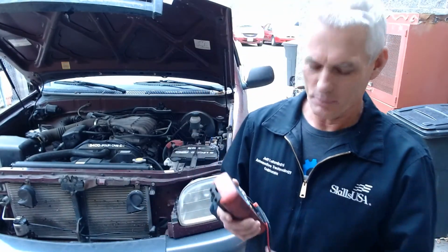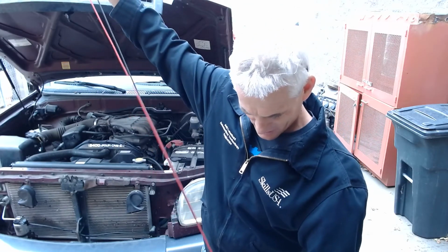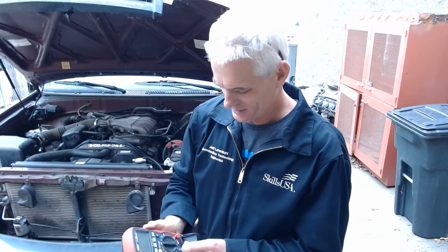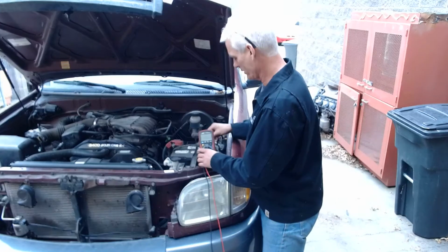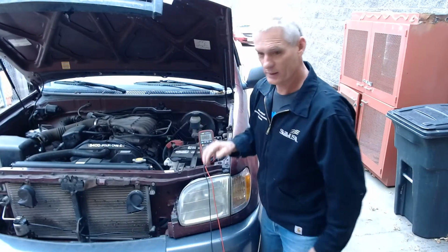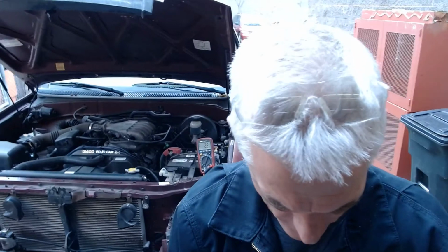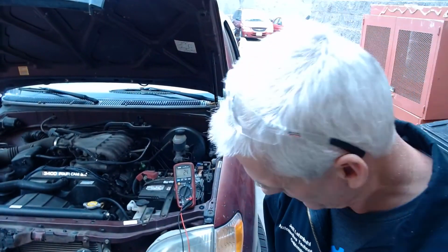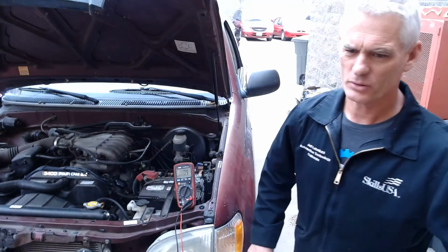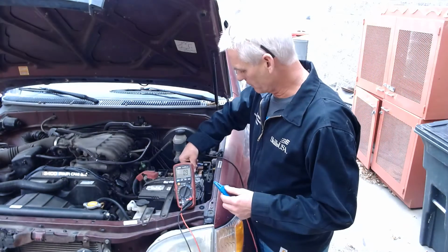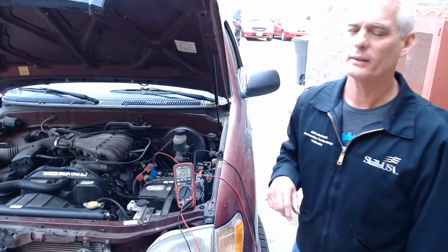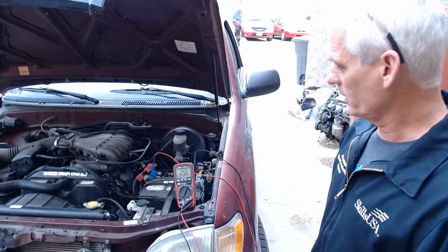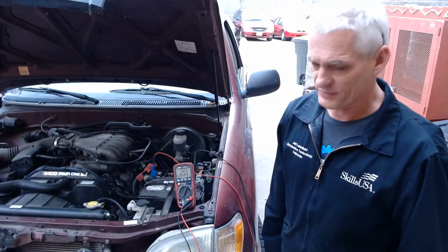So what started out as a fairly mundane kind of test proved to create a problem, which we're glad happened here instead of somewhere we're stuck on the road. So we'll put this voltmeter to V for volts, and I'll pull this forward, and you guys can read that. I can see that. I'm going to put the black lead to negative and the red lead to positive. Remember, if you hook it up backwards, it's okay. It'll just read backwards. So it's showing 12.56 volts.